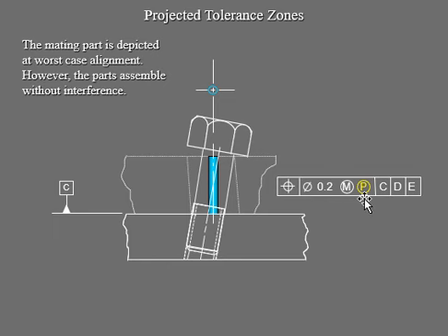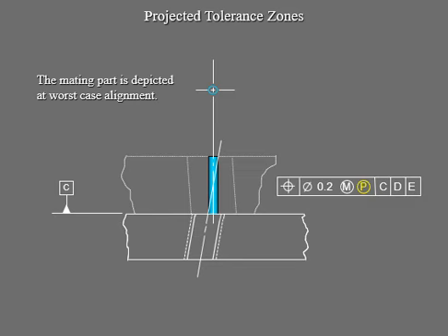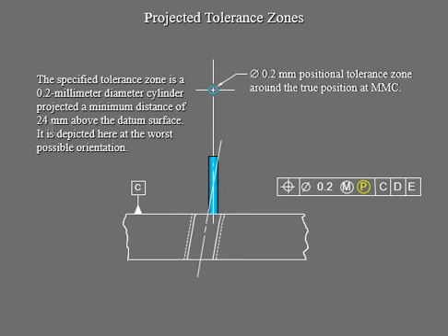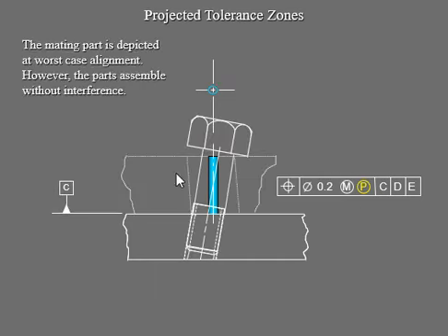So every time we define and put a value in it, the way that we machine got to be very careful, and we have to understand that our machining got to be in that zone, which is 24 millimeter. I'm going to go back one slide up here, so don't forget 24 millimeter. That's a lot, 24 millimeter of that height, minimum height. And that is going to make sure that that bolt is going to stay in that misaligned hole right in there.